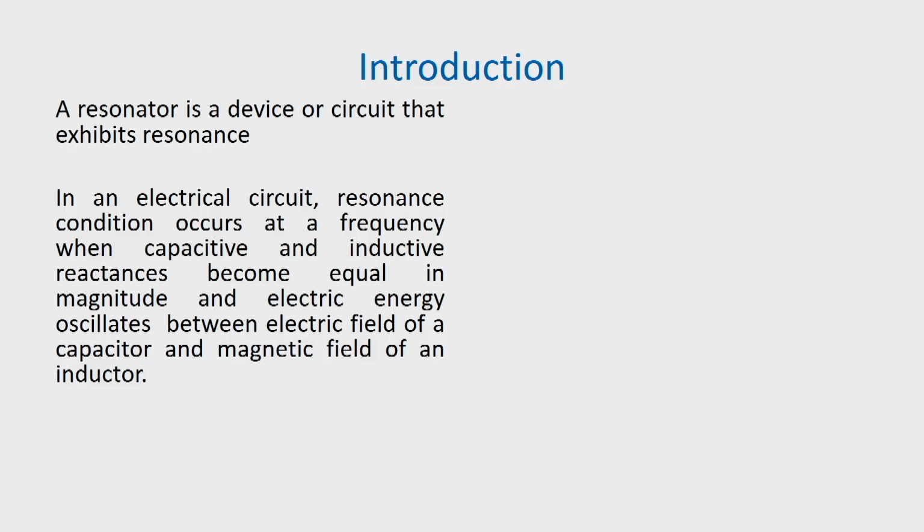So, a resonator is a device or circuit that exhibits resonance. In an electrical circuit, resonance condition occurs at a frequency when the capacitive and inductive reactances become equal in magnitude, and electrical energy oscillates between the electric field of a capacitor and the magnetic field of an inductor.